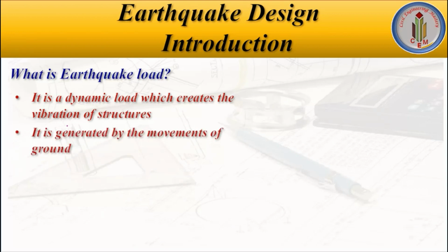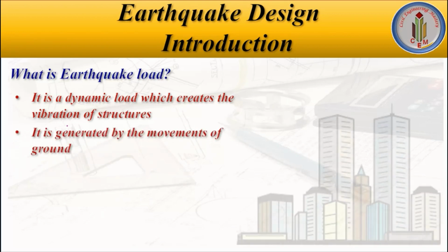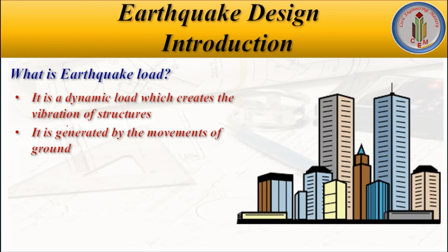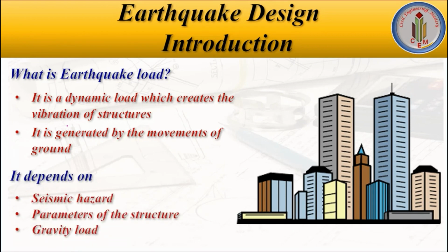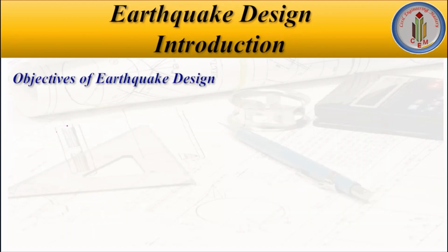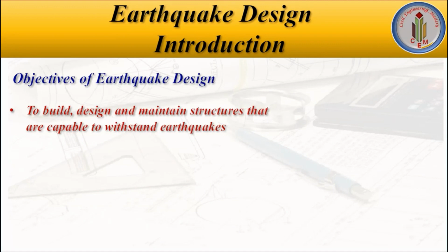It is generated by the movements of the ground. So when the building is resting on ground, if the earthquake occurs, it starts vibrating, or according to the ground movement, the building also reacts. Earthquake load depends on seismic hazard, parameters of the structure, and gravity load. When the earthquake load exceeds the moment of resistance offered by the structure, then the structure may collapse or even get damaged.